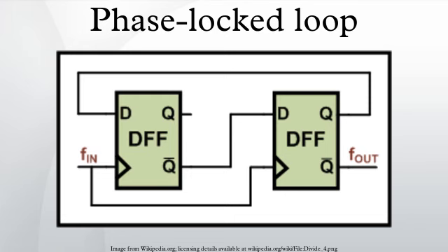Software PLL: functional blocks are implemented by software rather than specialized hardware. Neuronal PLL: phase detector, filter and oscillator are neurons or small neuronal pools. Uses a rate-controlled oscillator. Used for tracking and decoding low-frequency modulations, such as those occurring during mammalian-like active sensing.